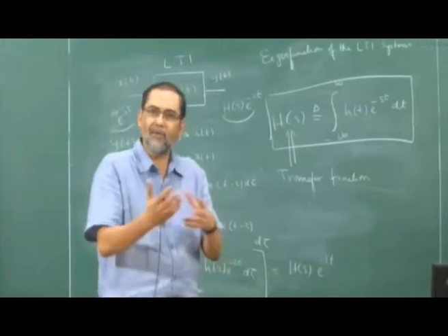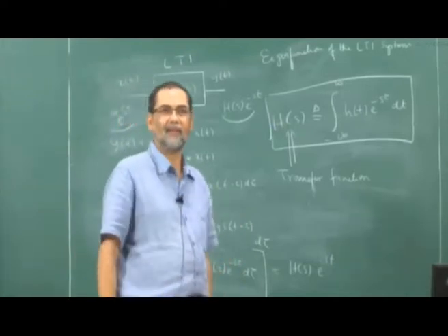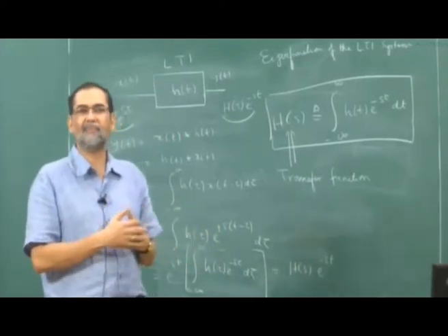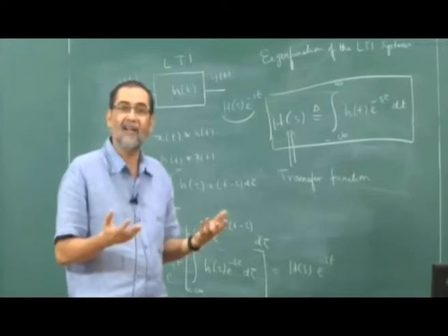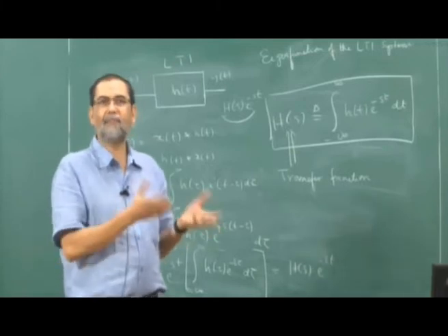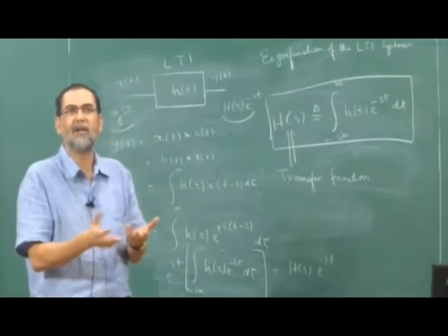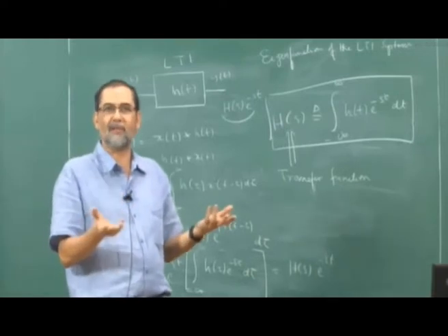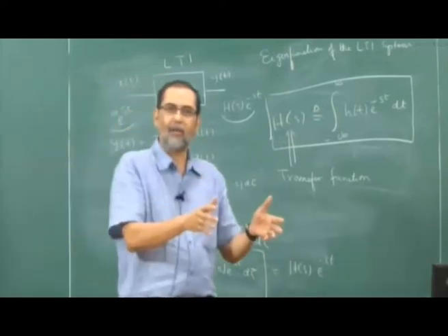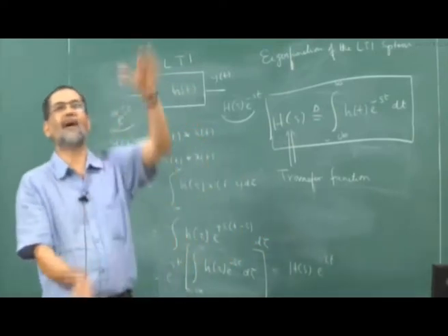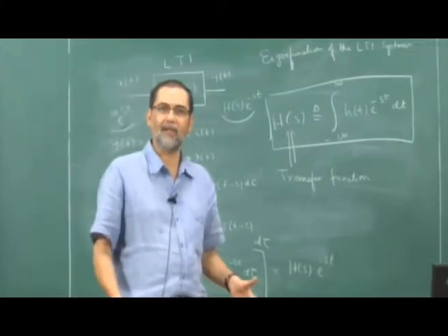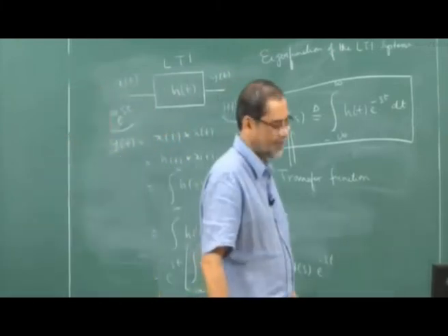The other way around, you have to see what is happening. If the frequencies are the same, is this LTI? You have to do more investigation. It may be that for that particular input the frequency is preserved, but for some other inputs it is not. But an LTI system says that no matter what the input frequency is, at the output you get the same frequency with some arbitrary change in the amplitude. If this property is preserved, then it is an LTI system. Okay, let's continue.